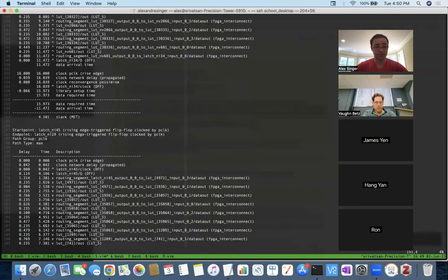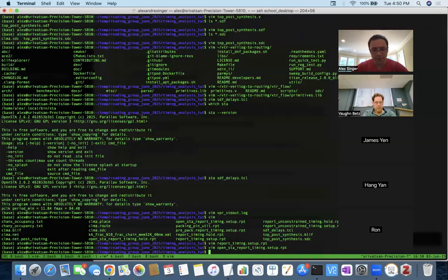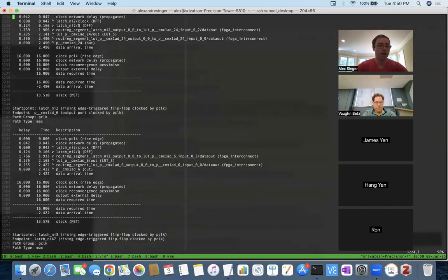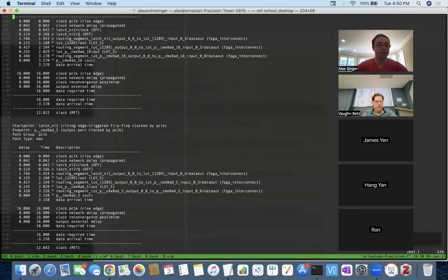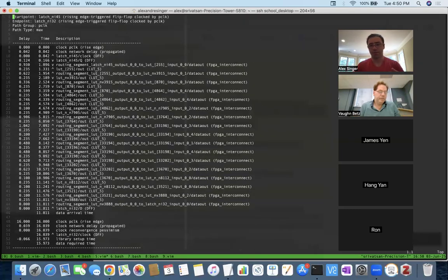And you can see that in this case, this is the OpenSTA one. I'm printing the 100 least slack paths, which is kind of a lot, but you can imagine you can add even more SDC constraints to try and further constrain your circuit by saying, okay, let's ignore maybe the path between this signal and this signal, which is something that you can't do in VTR presently. So it allows you to do more interesting static timing analysis.